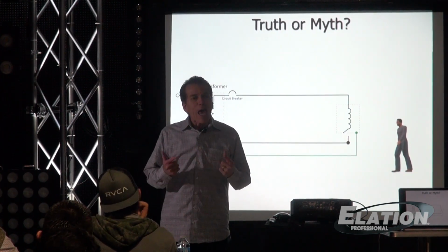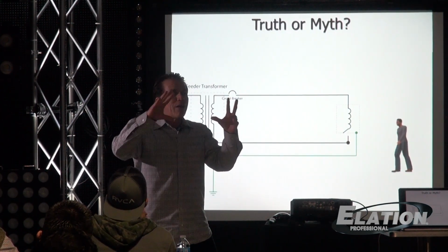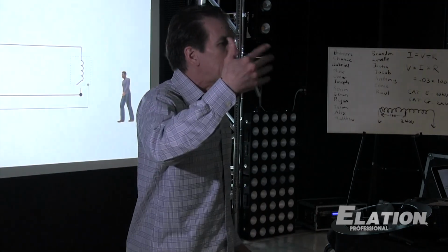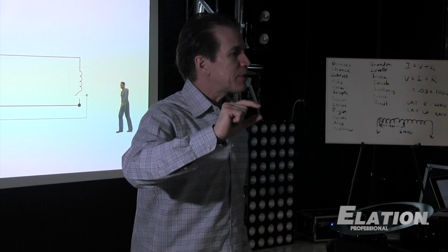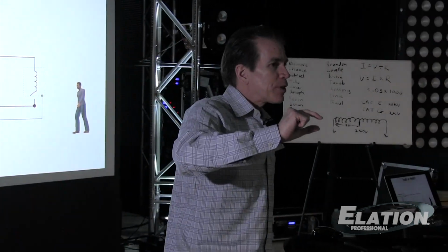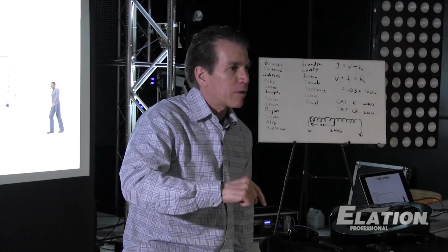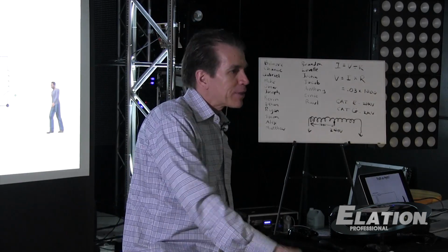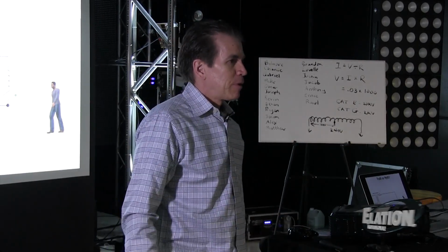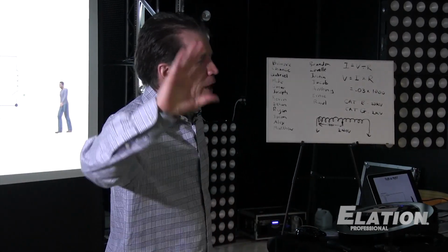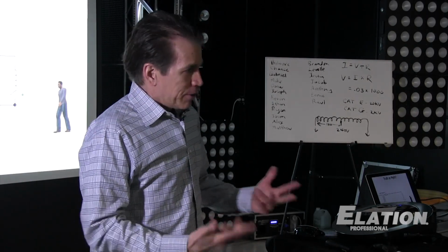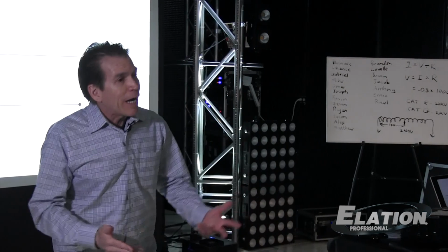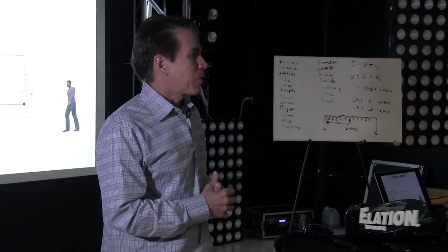So oftentimes what happens is the entire chassis of the honey wagon is energized, has a little bit of voltage on it. So when somebody's stepping onto the stairs and they've got one foot on the earth and one foot on the metal stairs, it shocks them. Or they can be standing on the ground talking and you touch the metal frame, you get shocked. So that's an example of why we don't like objectionable current.